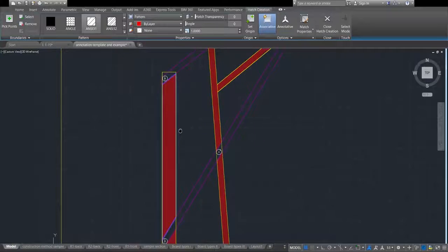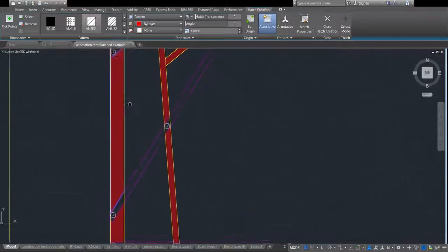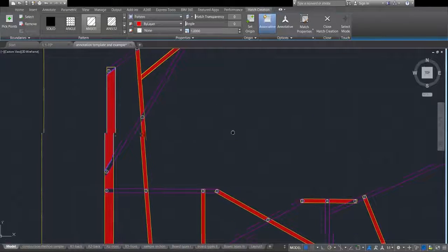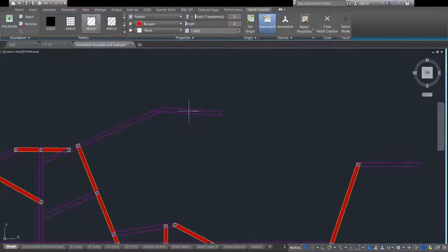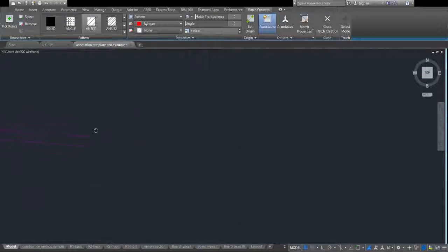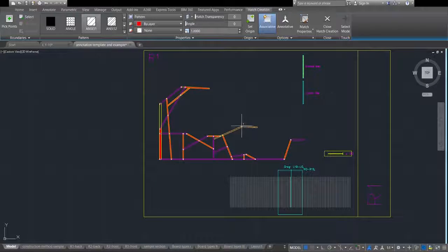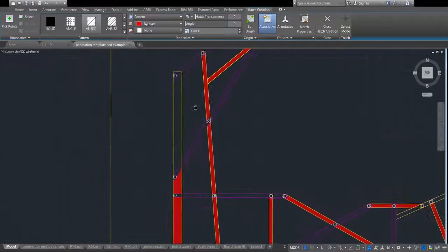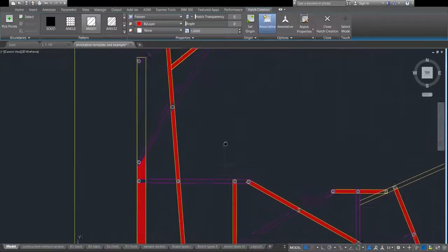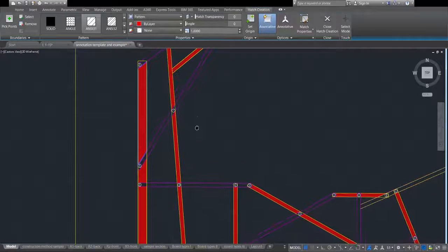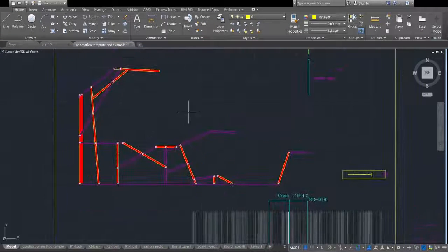One little quirk about this is that you want to make sure that all the boundaries of your hatch are within the view. So let's say I want to hatch this piece in, and you move your view all the way off this way, it actually worked that time. Usually it doesn't, and it'll complain about not knowing where the boundaries are. So if that happens, just move your view around. Also, sometimes when you undo, it'll undo more than one hatch. So just watch out for that.